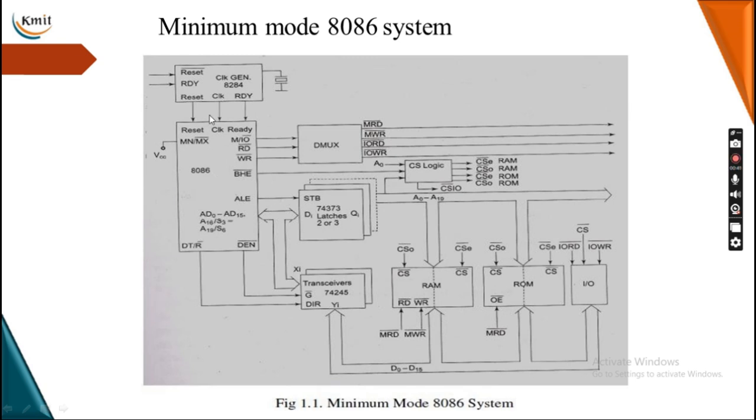So depending upon these controlling pins for reading or writing operation from memory or IO devices, and for selecting the RAM or ROM, high, even or odd, high or low order memory bank. ALE is being used for separating the address lines in the latch. As it is 20 bit, we require 3 latches in order to store a 20 bit address.